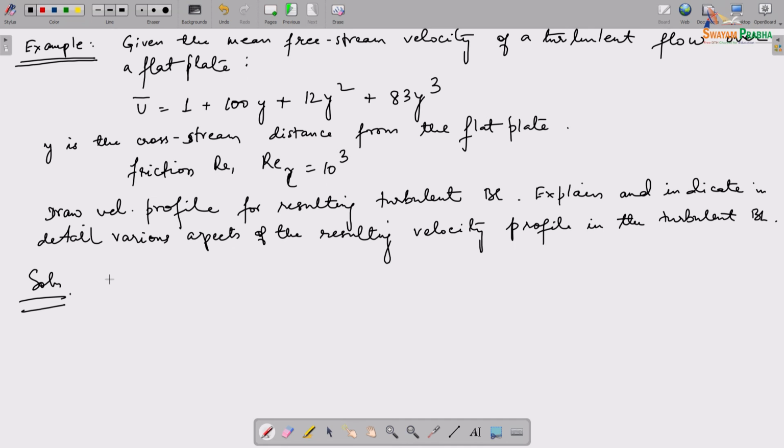Now, we know this from earlier, the shear stress near the wall is entirely a viscous contribution, because it is a turbulent flow. We have been given a mean velocity, which is fine, but we do not have any idea about the turbulent quantities, which are the u dash and the v dash. However, at the wall, the shear stress is dominated primarily by the viscous force.